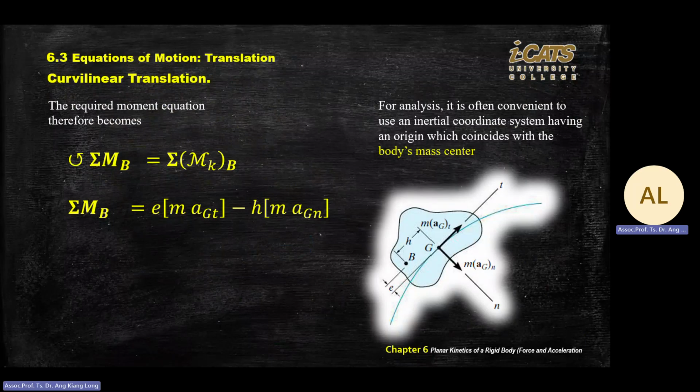Free to rotate means there is no resistance there. So in this question, you're focusing on the back wheel that is locked, always slipping. Ignore the mass of the wheel. The coefficient of friction is given, meaning you need to find the friction force over here.